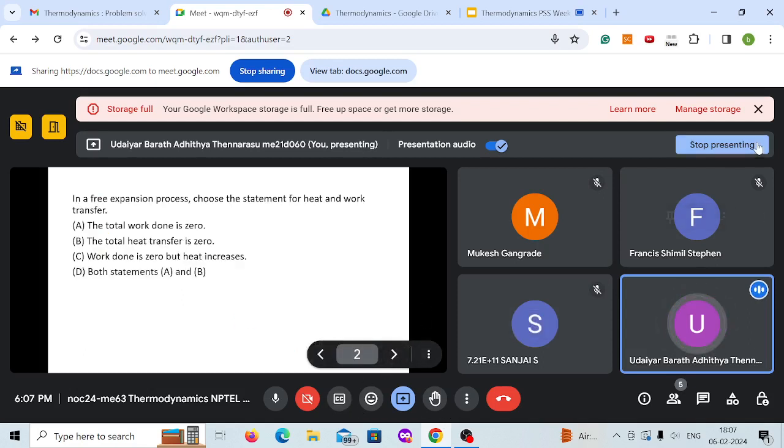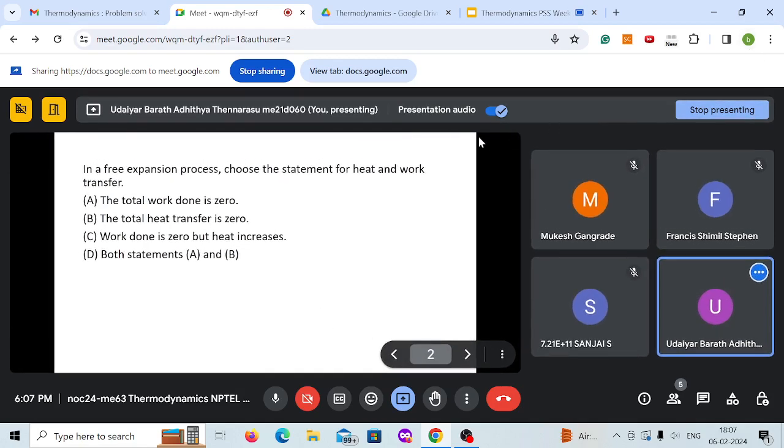So in the zeroth law, you come across it when you have a fever or something, and you put a thermometer. There the temperature you read, there you are seeing the zeroth law of thermodynamics. It states that when two bodies are in thermal equilibrium, meaning both are at the same temperature, and a third body is in equilibrium with one of them, the first and third will also be in equilibrium. So it's basically to estimate the temperature, because that gives you an idea of the energy. When you put a thermometer, you are making the thermometer come into equilibrium with your body to measure the temperature. So that's an example of the zeroth law of thermodynamics.